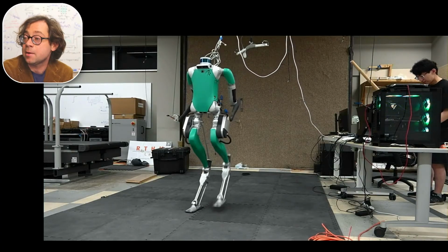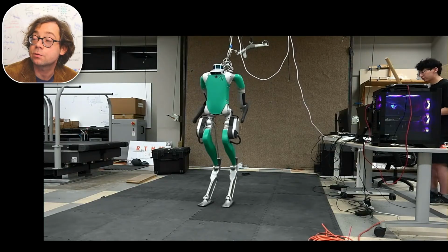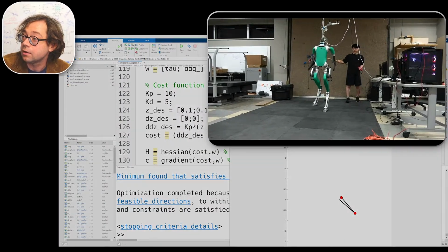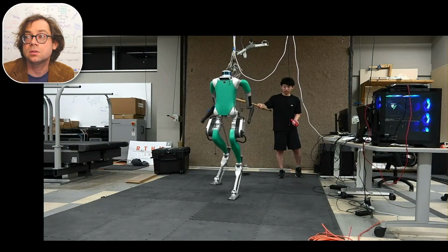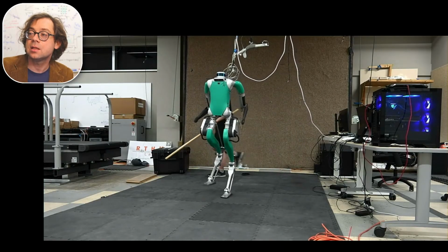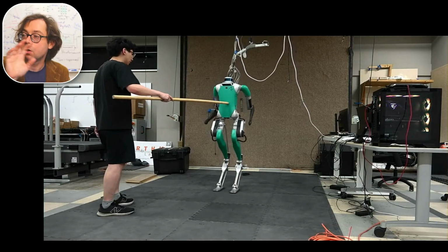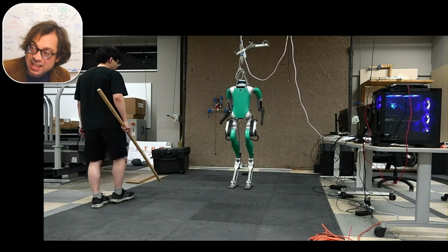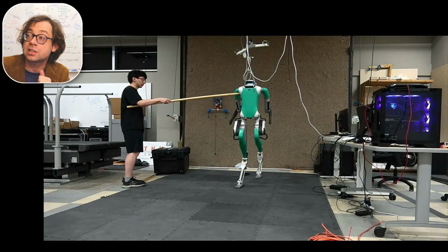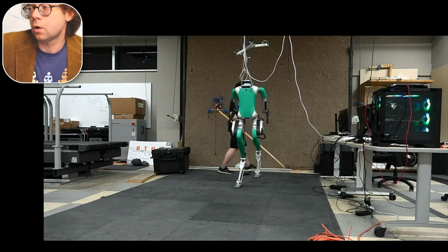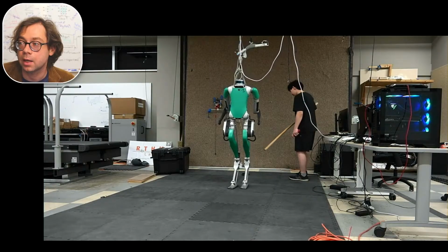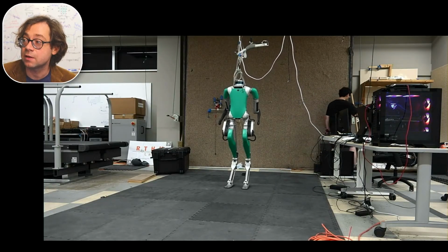What else is different? The dynamics are much more complicated. We have a lot more degrees of freedom. How many degrees of freedom? The arm I just showed you is 2 for that arm. Here you have 20 motors, so there are 20 actuated degrees of freedom. Then the base itself has forward, backward, left, right, and all 3 rotations, yaw, pitch, and roll. So that's 26 degrees of freedom. In addition, there are 2 springs on each leg. So that's 30 degrees of freedom. So theoretically, the size of the q vector is 30. But it's still a convex quadratic program, so it still runs fast enough that you can run it on this robot.